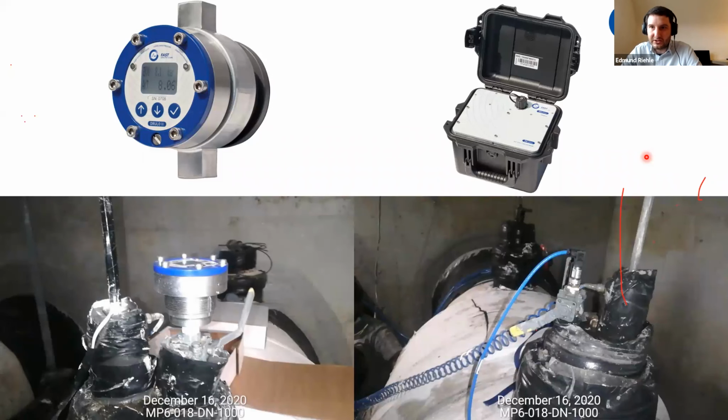Some more pictures of the installation and the devices we used here. The pressure logger has a 1/2-inch thread, and the additional sensor for attaching to the ZM Ultra also has a 1/2-inch thread, so we connected it directly to the air valves on the cooling pipes and monitored the pressure along the run of the pipe. In each chamber we placed 2 loggers, one on the supply and one on the return, again to have a full data analysis of what is happening.